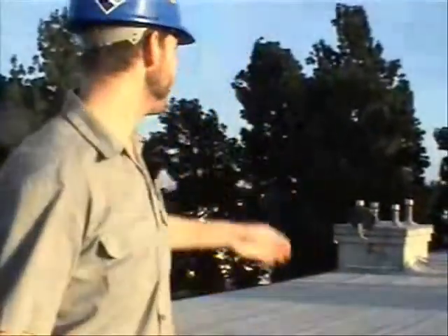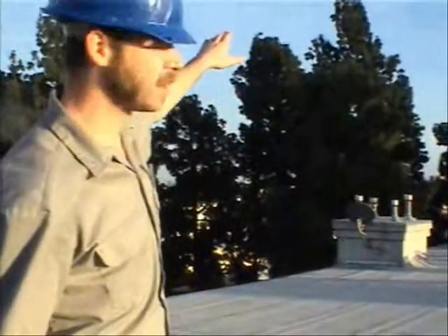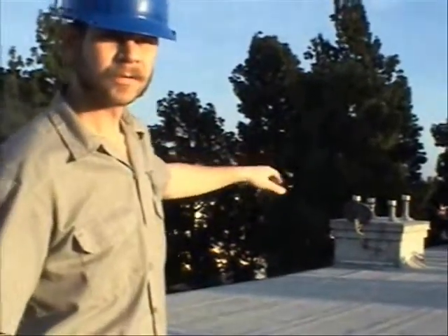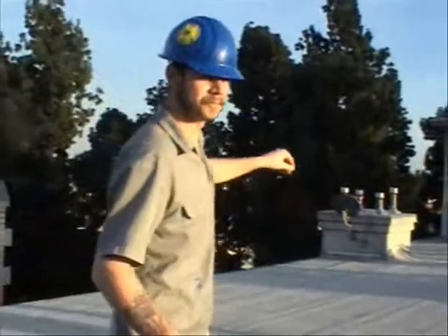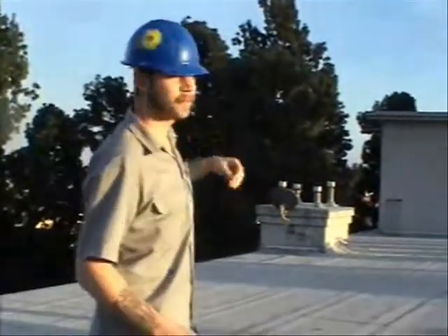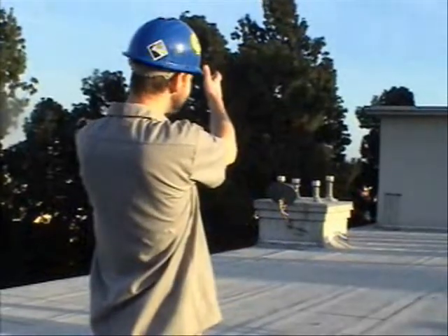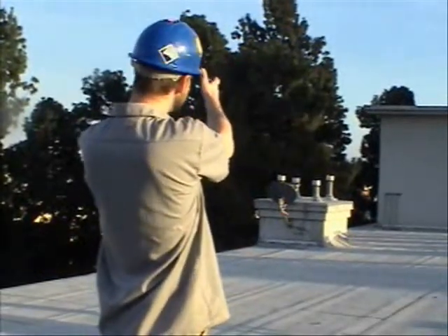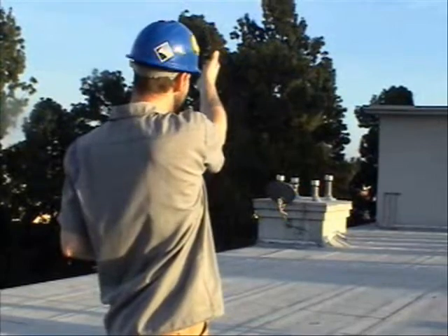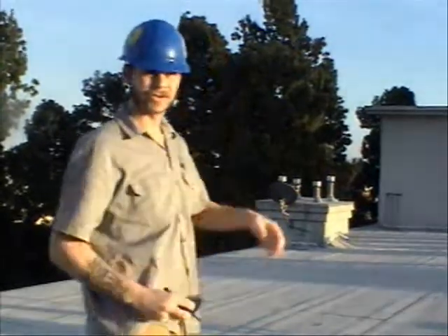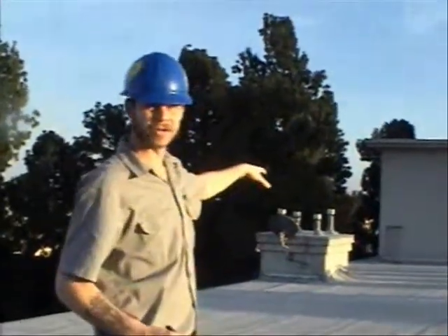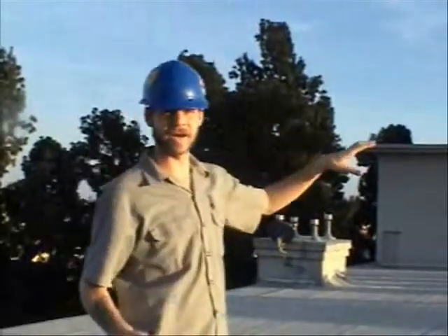Then we're going to take a protractor and we're going to determine the angle that sits above the horizontal axis. From that we're going to figure out approximately how wide it is, about 5 degrees wide, determine how high it is. From that we're going to be able to determine the year-round shading using our sun charts. Go back inside, I'll show you how to do all of that.